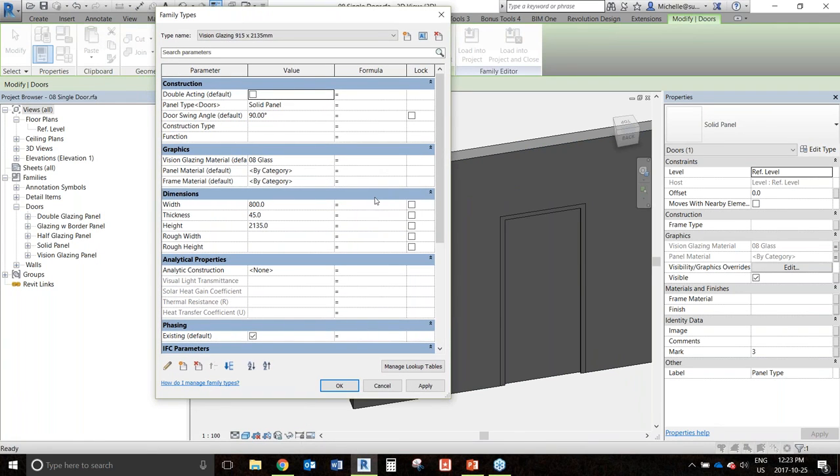So this is where you're taking that family up to the next level. Instead of having 4 different families for representing the different types of panels, I have nested the panels into this family, making it one family instead of 4 or 5. So then you have the ability to just switch this out to a different panel, and it switches out the family for you.